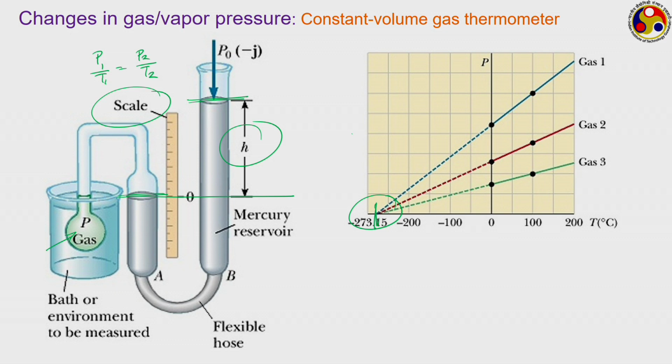Now, constant volume gas thermometer generally is used as a reference for calibration purposes, but may not be for industrial use, because it is generally fragile. Again, you need to keep this one in contact with the body where we want to get the measurement. It is quite difficult to use for practical purposes, and that is why it is restricted only to laboratory purposes.